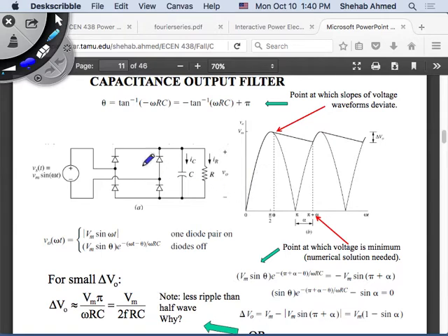The explanation we used last time we'll repeat this time. So there's a value of an angle theta here for the case where I don't have a resistive load, or for the case where the capacitor value is infinite. The capacitor was originally discharged, then it is charged through the supply until the peak value of the voltage, and then it remains at that peak value.